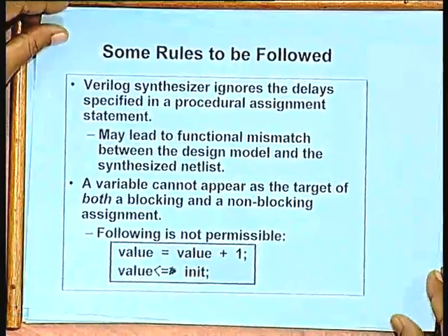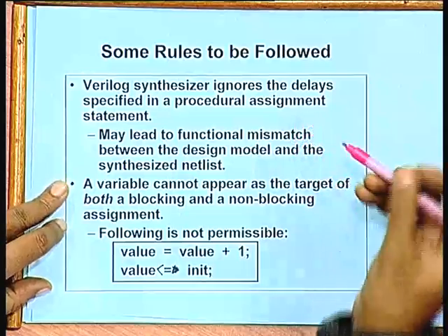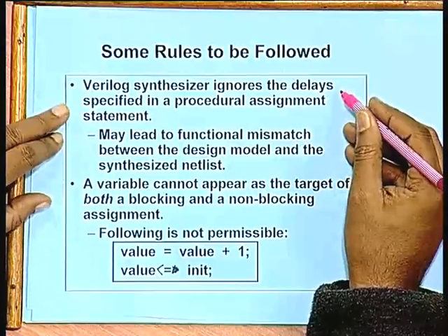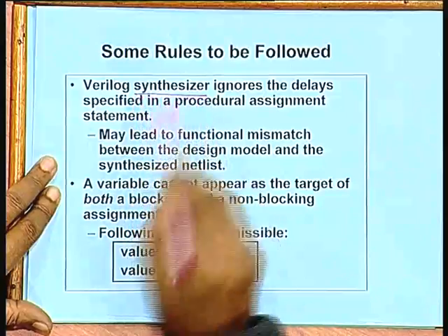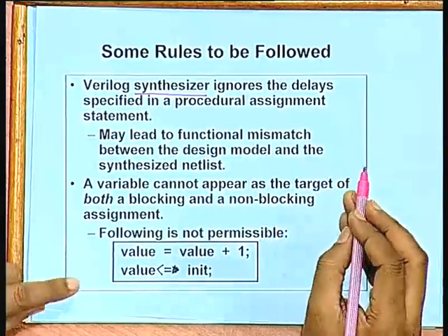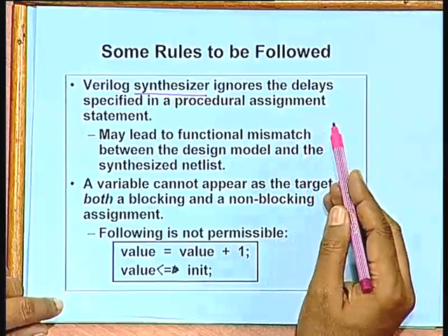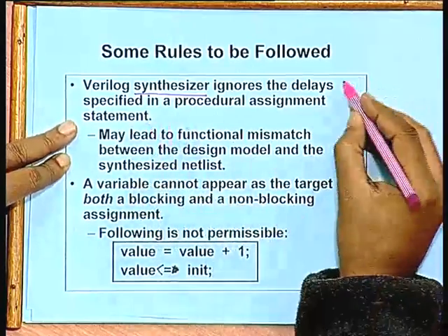So, some rules you need to remember and you need to follow. I have repeatedly told this, that the user can specify some delays along with each of the blocks. Now, whenever you are carrying out synthesis, the delays are all ignored. Delays make sense only from the point of view of simulation. Okay? But there is one problem here.